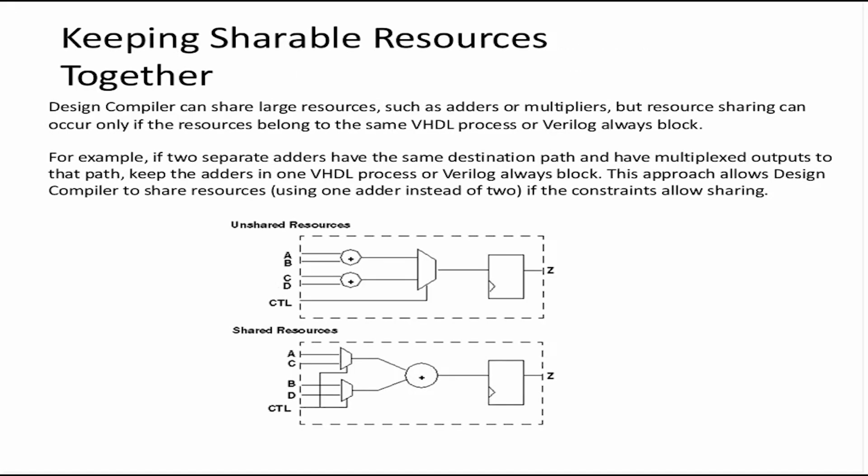Another guideline is keeping shareable resources together. Design Compiler is actually pretty good at sharing resources such as adders or multipliers, but resource sharing can only occur if the resources belong to the same Verilog always block.